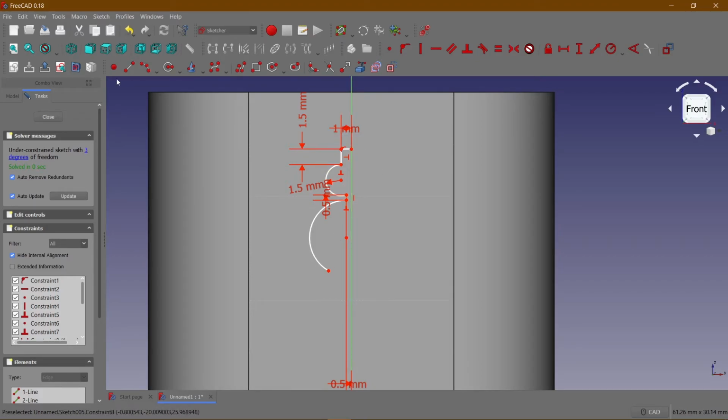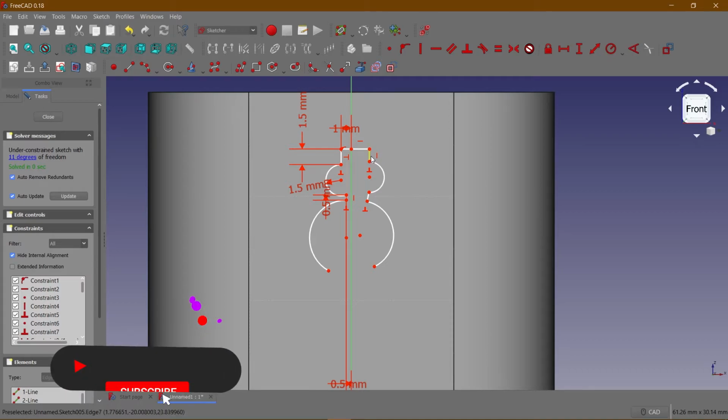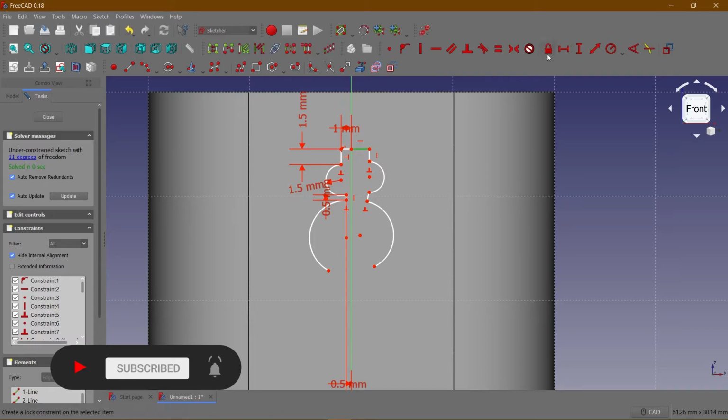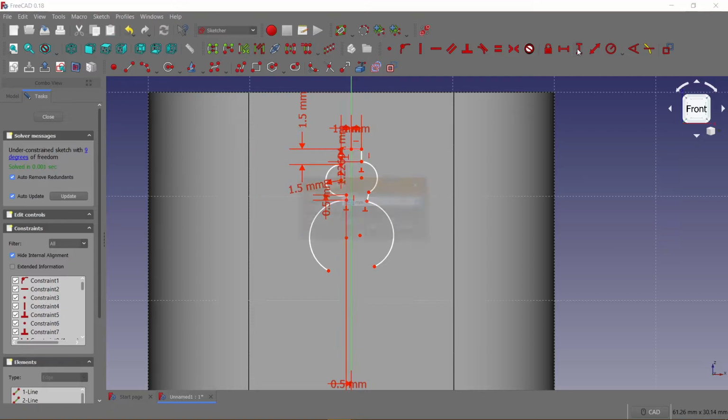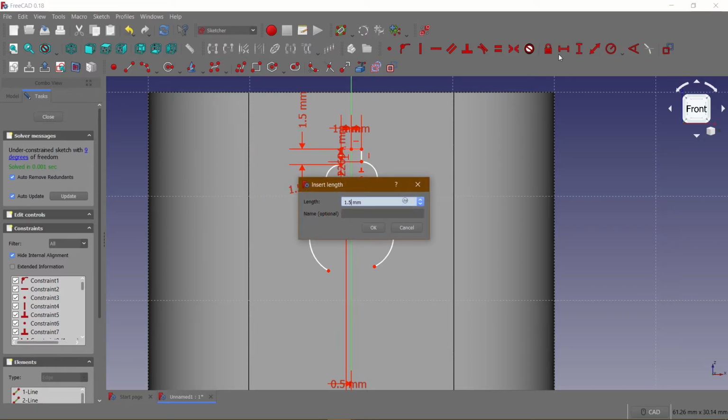And then I'm going to create it on the other side also. So this is just a half. I'm going to create it on the other side again. So I'm going to click on the polyline tool again. Start from the coincident of this point and create a mirror image of that sketch. So M to change it to an arc. So I need a line now, and then another arc. So something like this, and okay, first, this has a horizontal length of 1. This is 1.5.